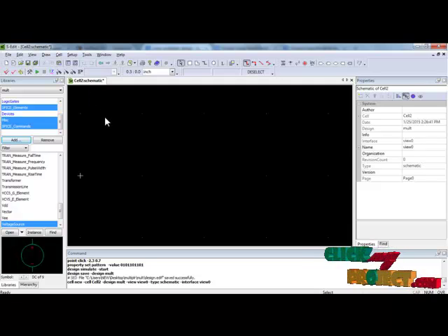Each cell should contain a different CMOS design. The next process is to set up the simulation. Pressing this icon will lead you to setup simulation. In the setup simulation you have to set the maximum time duration for the design, in nanoseconds.